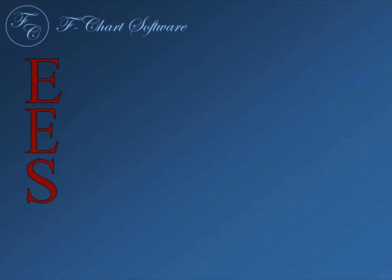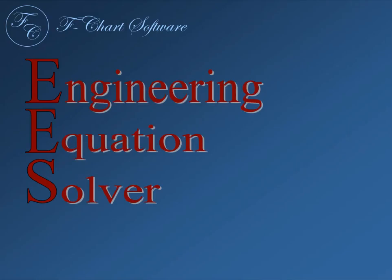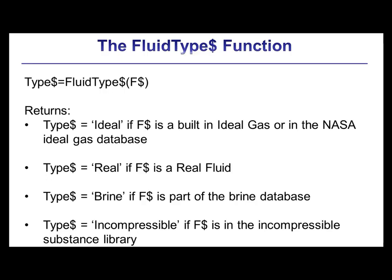EES, which is pronounced "ease," is an acronym for Engineering Equation Solver. We have seen that there are a variety of property models that can be used in EES to obtain the properties of fluids. These include real fluids, ideal gases, incompressibles, and brines. The exact protocol for obtaining the properties of these different types of fluids is not the same, and therefore it may be difficult to switch between, for example, an ideal gas and a real fluid within an EES model. The FluidType function makes it possible to automatically detect the type of fluid model that's being used and therefore adjust the EES code accordingly.